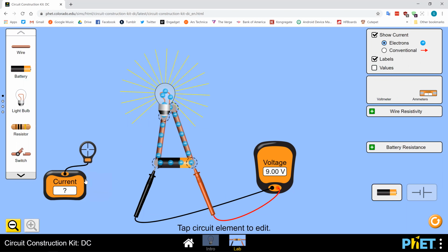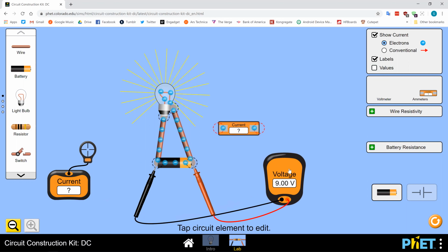The other way you can do this is by using a traditional ammeter. And this one is complicated in that we need to break the circuit to put this in. This non-contact one, I just have to hover over it, and they do make ammeters like this. For this one, what I'm going to need to do is to break my circuit.